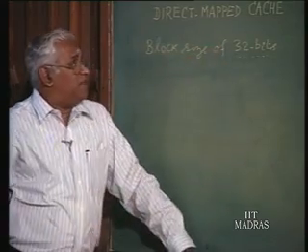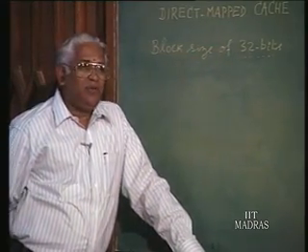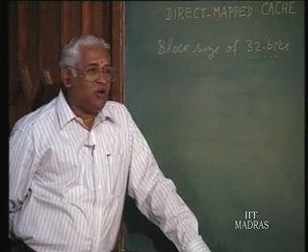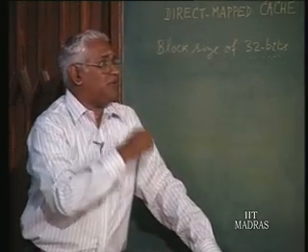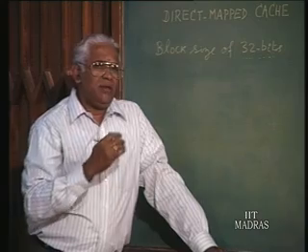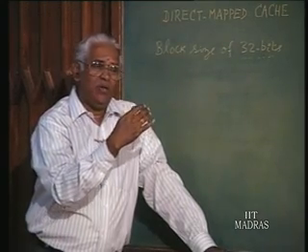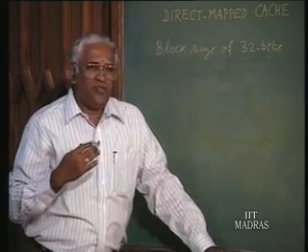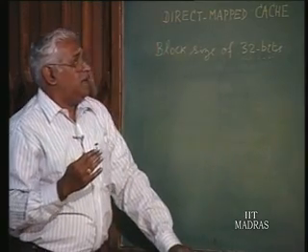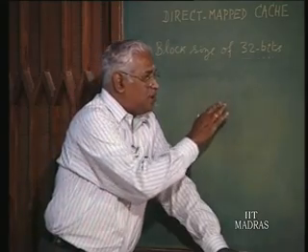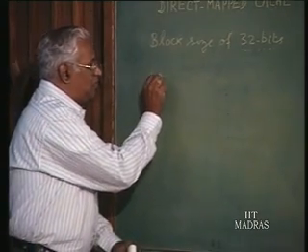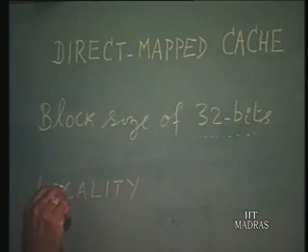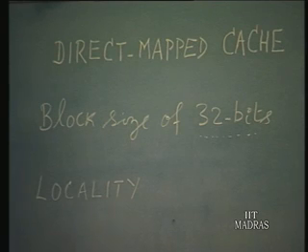Now, just by saying that the cache has 32 bits, we do not know what exactly the CPU deals with. It may be 16 bit, it may be 32 bit, it may even be 8 bit or 64 bit, whatever it is. Nothing is known about it. Now, when a program is organized and then subsequently executed instruction after instruction, we have also seen that the subsequent instruction cycles will involve instructions in adjacent locations. So, as far as the CPU accessing the data is concerned, it is meaningful to assume that subsequent bytes of data in the memory will be accessed. This is what we explained earlier as the principle of locality, that is something which is local. In this particular case, that is something which is immediate or the next word, next byte, and so on and so forth, based on the principle of locality.